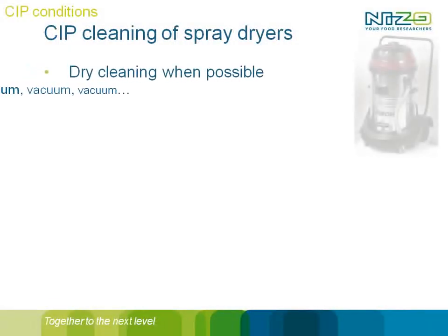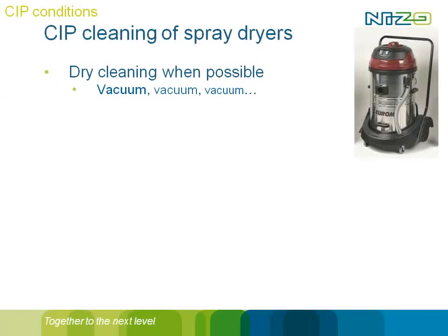Something to mention about spray dryers. If you want to clean a spray dryer, I would say, well, don't. If you can have a dry cleaning, do it. In that case, you should be able to vacuum, so remove the powder within your installation.